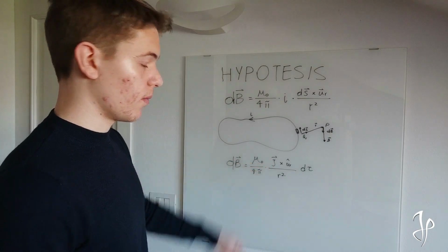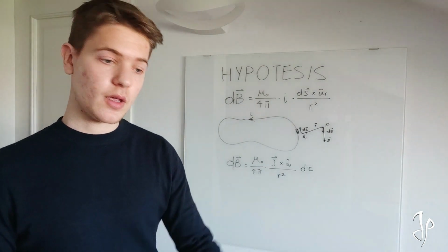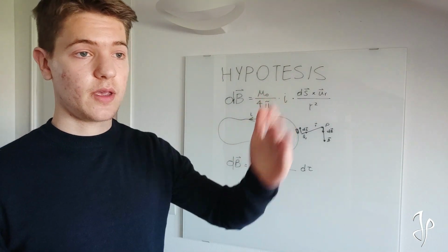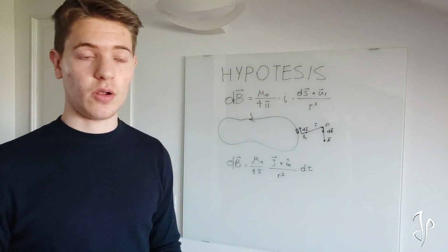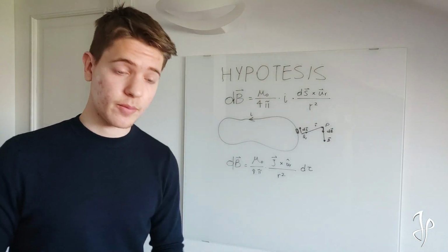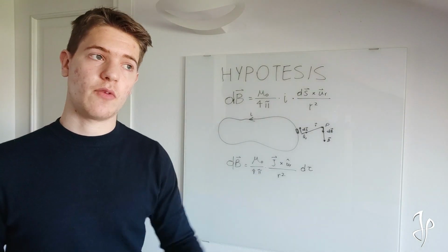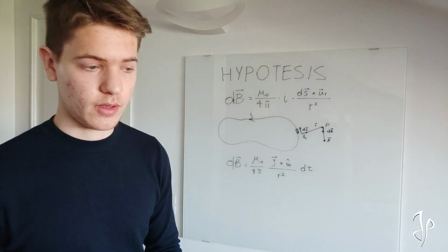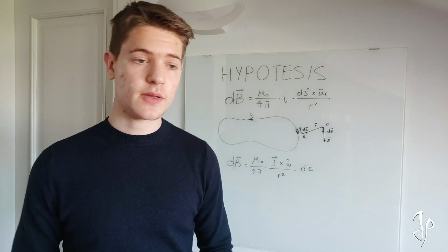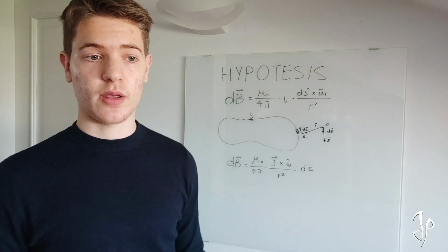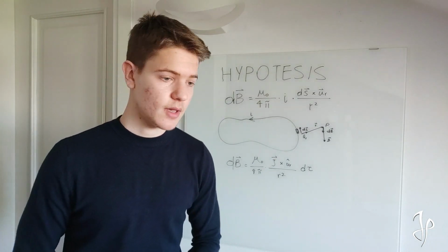So you have more information about current, because thanks to the current vector J, you know how the current is flowing throughout the section of the conductor and not only the length of the conductor. So this more generic expression is the one you have to use if you want to work with conductors characterized by multiple dimensions. So, for example, I'm talking about planes, conductive planes, or more generic conductive volumes.